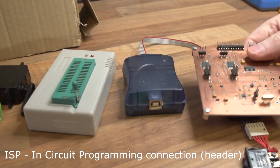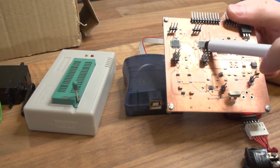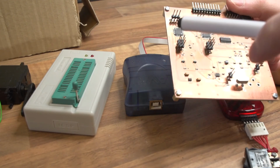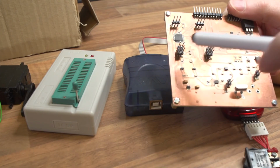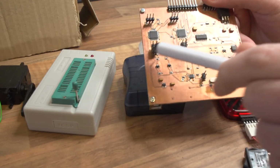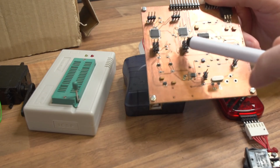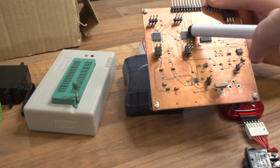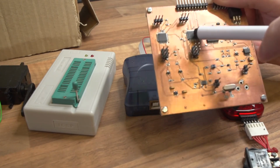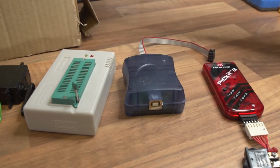This is a board I made some time ago. It's a memory device for a radio, and this has got two ATMEL chips on. These are surface mount versions. These are both microcontrollers. There's two of them on here, and you can program them through these DIL headers here. So using this programmer, you can actually program those chips by connecting to those DIL headers, what they call ISP connections, in-circuit programming connections, because the chip stays on the board. You don't have to remove the chip, thank goodness, because they're quite difficult to solder. So they stay on the board and you program it while it's in circuit. That's an in-circuit programming connection.